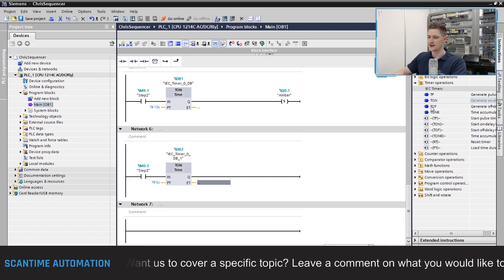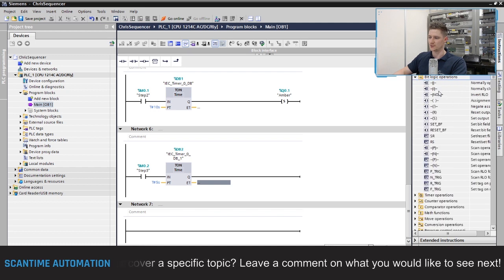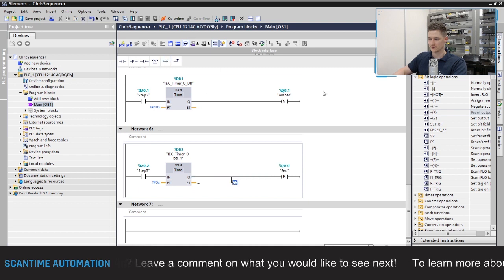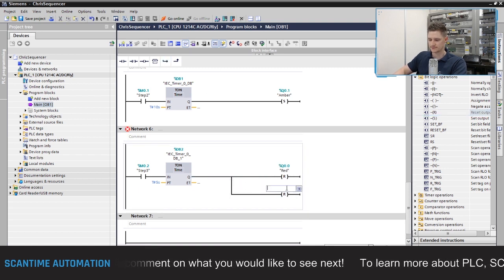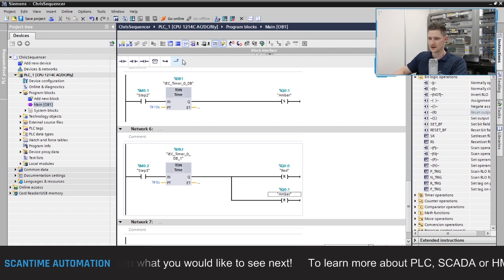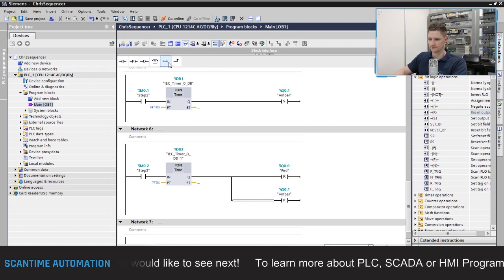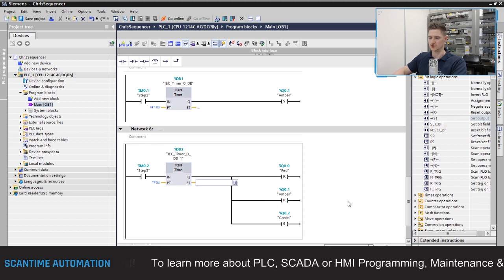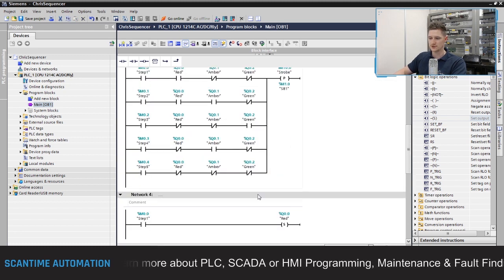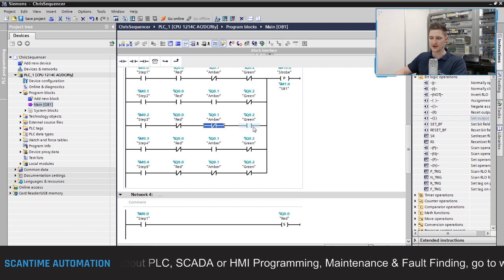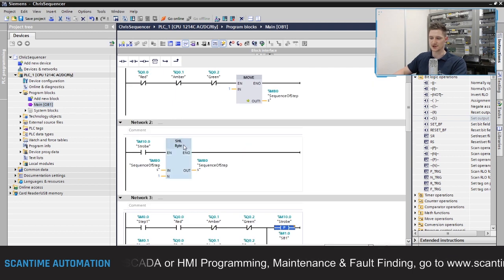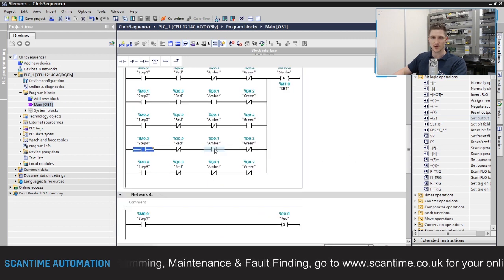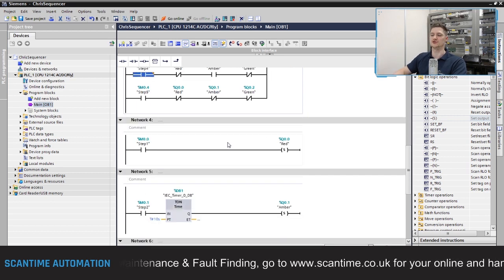Like that. And then what we want to do after those 5 seconds is reset the red lamp, reset the amber lamp, and then set the green lamp. There we go. Again, now we're at step 3 with the red lamp off, the amber lamp off, and the green lamp on. It's going to trigger our strobe signal once again, shifting the bits one place to the left, turning on step 4, and now we need to have the amber lamp on by itself after a 10-second period of the green lamp being on.